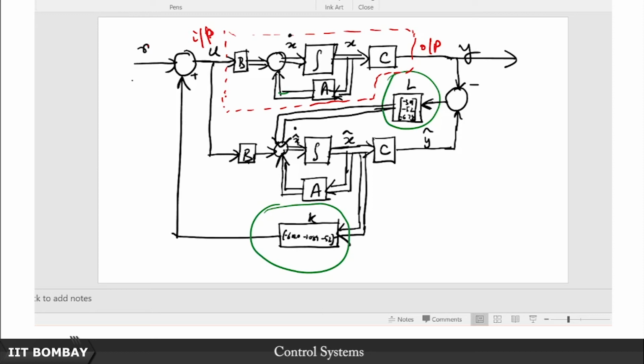In fact, joint controllability and observability is the same as minimality, right. We have seen that whenever you have no pole-zero cancellation in a particular transfer function, it means that the system is going to be minimal, and that also implies that the system is going to be both controllable and observable. And if a system is controllable and observable, which is what brought us to the last part of this course, then we saw that we will be able to design a controller to place the poles of the system anywhere we like. That is the beauty of the whole thing.